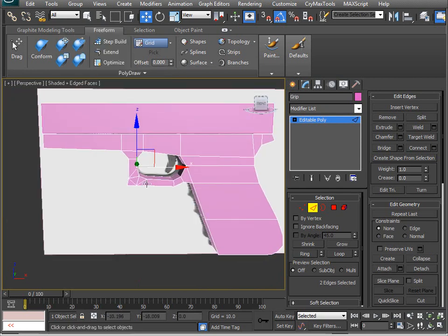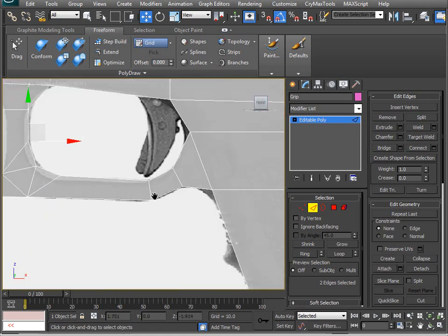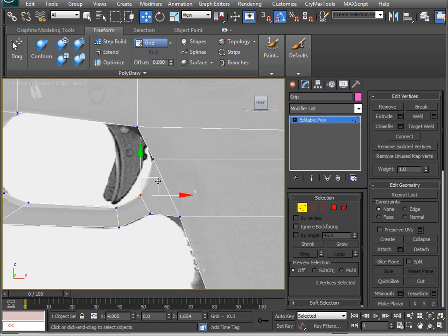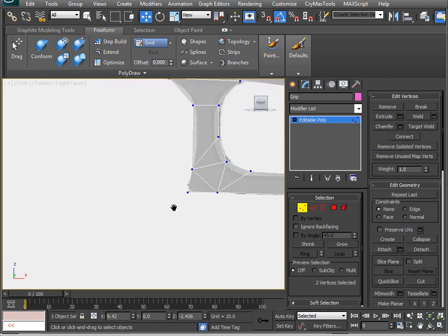Okay, I'm just going to Alt X on it again, hit VF so I can go back to this view, which is my handy modeling view. And I'm going to move that a little forward. That should be down a little bit. Now you see I can potentially break my form, so I'm going to go back to edge when I move that down. And then put that to none. It's a good habit to put that back to none.